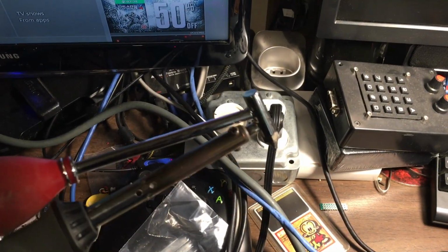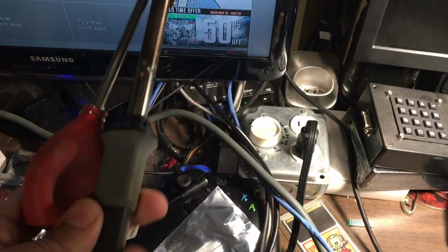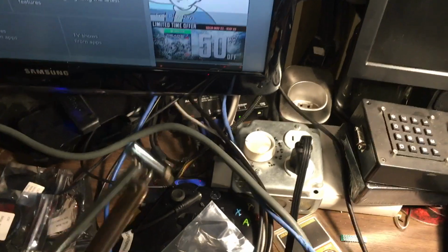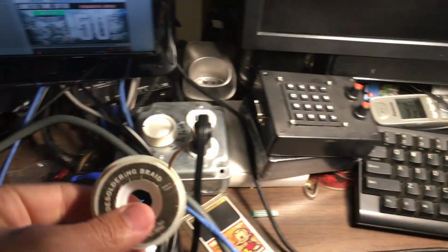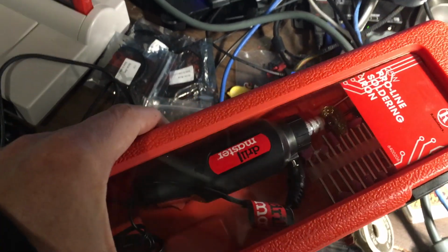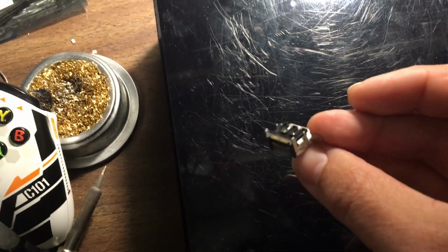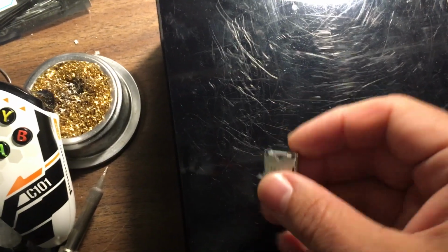And I have another tool here, which is a solder sucker. It has this little bulb. You squeeze it. It itself is also a soldering iron. So I have a couple different tools here. I have a desoldering braid. And I also have this little Drill Master kit I got from Harbor Freight for about $10, and this allows me to cut metal. So what I might do is cut some of these legs off of the port and then desolder this here.